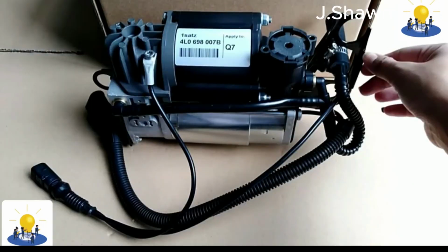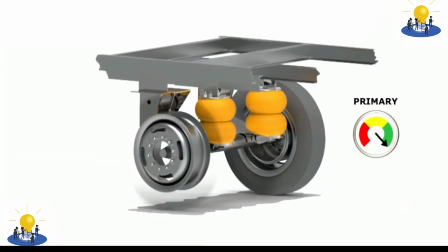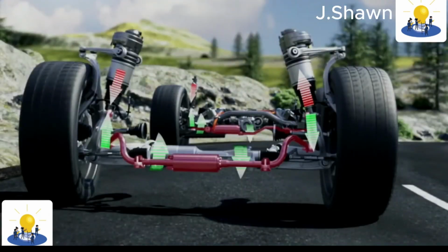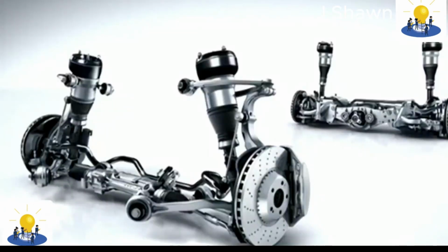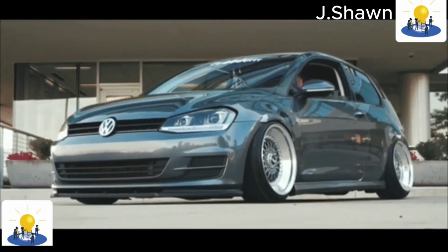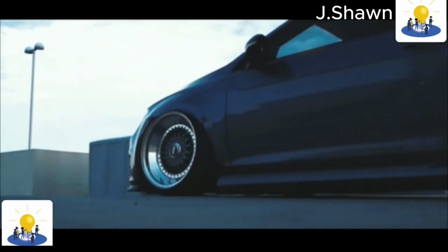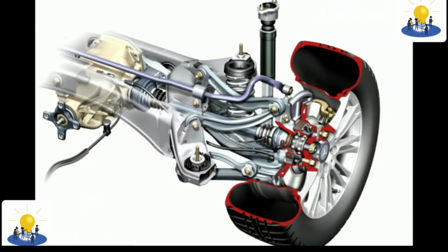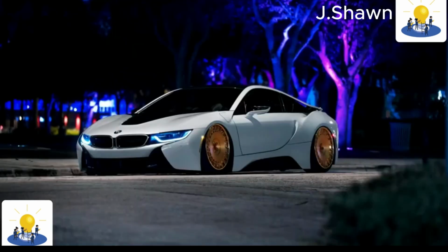Common air suspension problems. Airbag or air strut failure is usually caused by wet rust, due to old age or moisture within the air system that damages it from the inside. Air ride suspension parts may fail because rubber dries out. Punctures to the airbag may be caused from debris on the road. With custom applications, improper installation may cause the airbags to rub against the vehicle's frame or other surrounding parts, damaging it. The overextension of an air spring, which is not sufficiently constrained by other suspension components, such as a shock absorber, may also lead to the premature failure of an air spring through the tearing of the flexible layers.